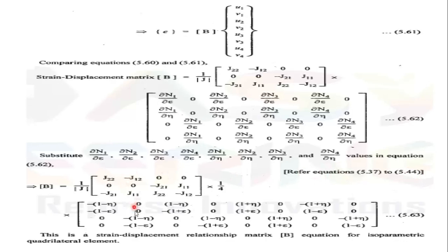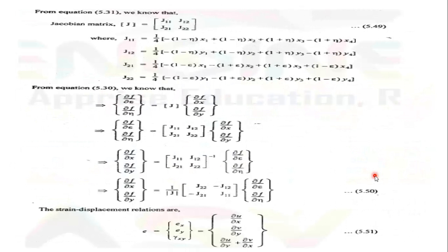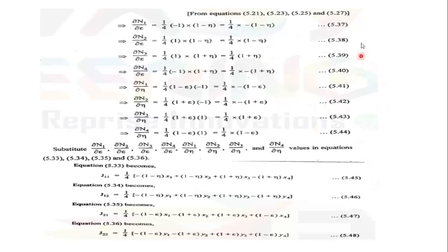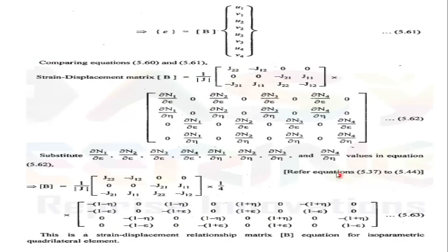I just substitute these values, that is, ∂N1/∂ε, ∂N2/∂ε, and similarly ∂N1/∂η, and so on, in terms of epsilon and eta. We have already derived those values, so we just substitute them directly. So B is equal to 1 by mod J; in terms of epsilon and eta, we get 1 by 4 as common. So this strain...